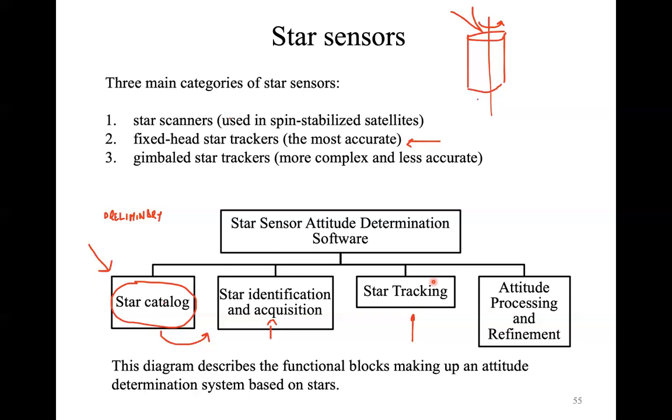And so probably in that case, one of the three star trackers is not operating. When you are going to reuse that star tracker, you have to reinitialize the instrument, so reload the star catalog and the device. So in principle, you should always work with the star tracking mode, but there are different situations during a mission where that is not really possible.